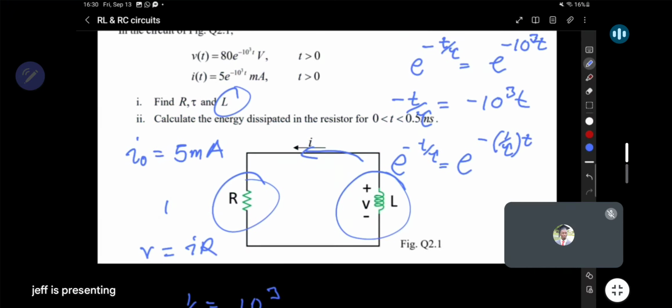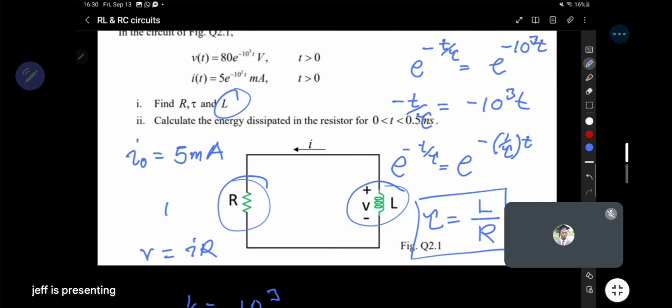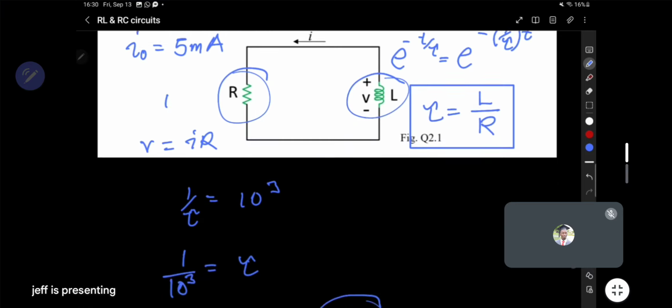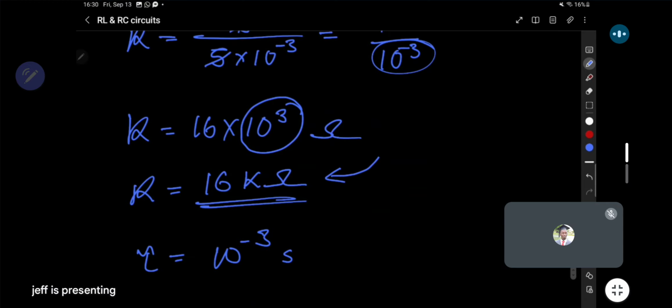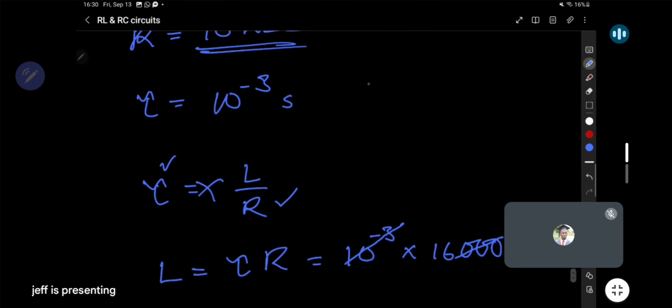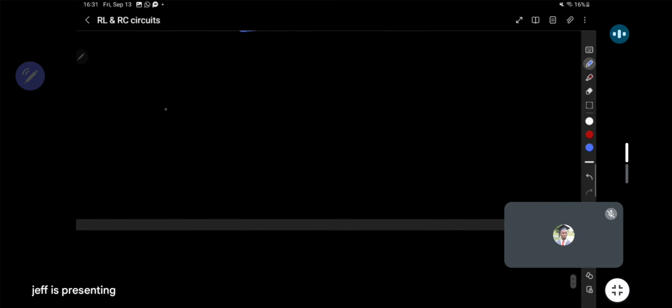So we observed that for our circuit, what we have is a source-free RL circuit, as in it has an inductor. And we saw when we were introducing the concepts that if it is an inductor, the time constant was presented as the inductance over the overall resistance in the circuit, R. So this is what we saw when we introduced the source-free circuits.